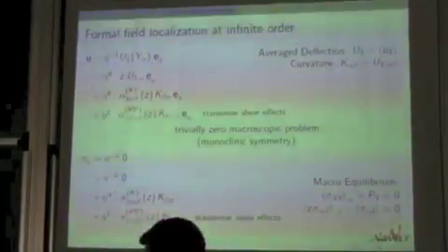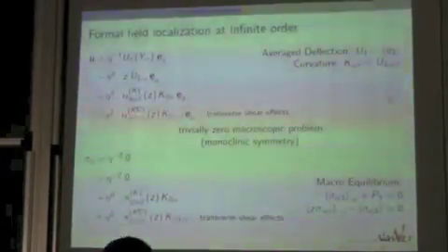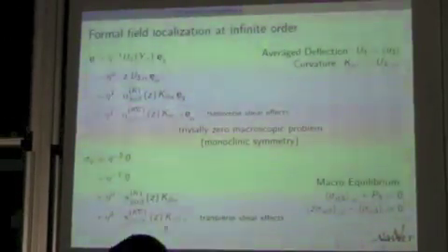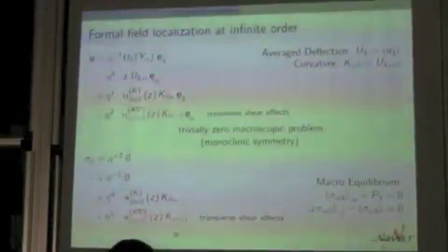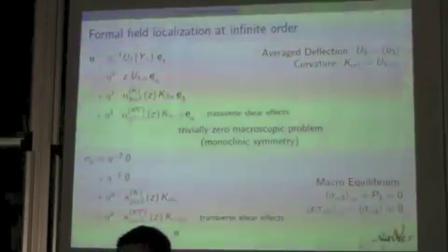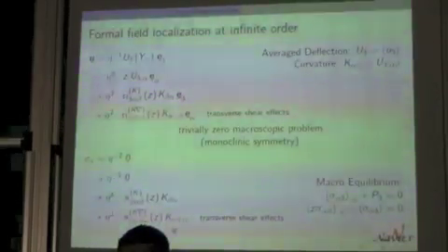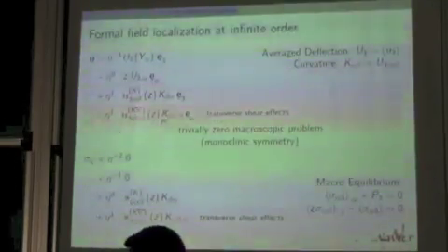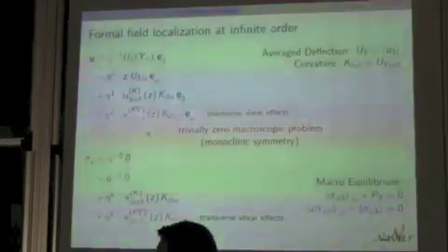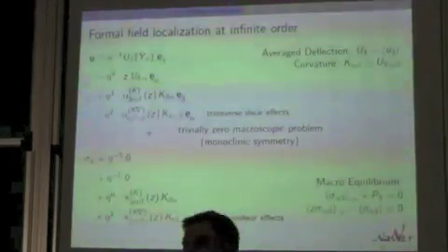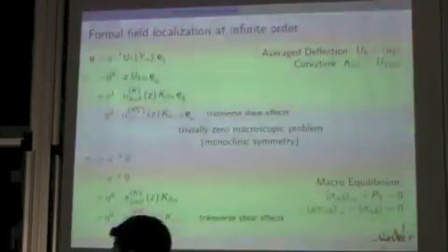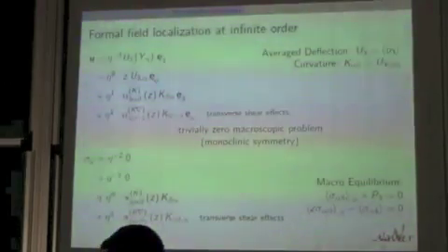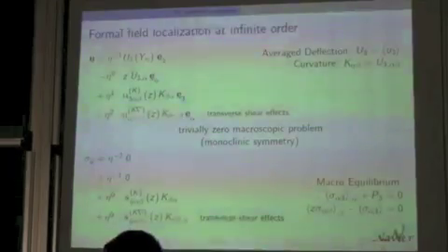higher in orders. If you go higher in orders, what you get is you have a very interesting stress distribution related to the gradient of the curvature, which carries or encodes the transverse shear effects inside the plate. Okay? And in terms of displacement, you have a correction which is, let's say, related to transverse shear effects, but which mixes some different contribution mechanically speaking. I cannot go too much into details.